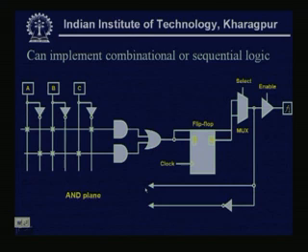Now, some more advantages are also there for this fixed OR plane. See, earlier it was only combinational. Now, we can realize sequential logic also by using a PAL structure. This output plane, normally the OR plane, we call the output plane because the output function is taken from the OR plane.